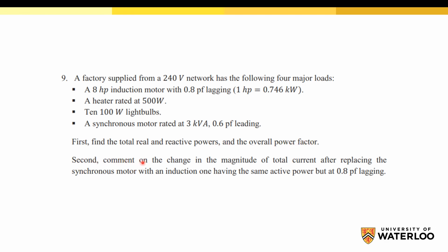Second, comment on the change in the magnitude of total current after replacing the synchronous motor with an induction one having the same active power but 0.8 power factor lagging. So we will change this load with one having the same active power. This is not the active power, this is the S value. And we need to change this 0.6 power factor lagging to 0.8 power factor lagging.